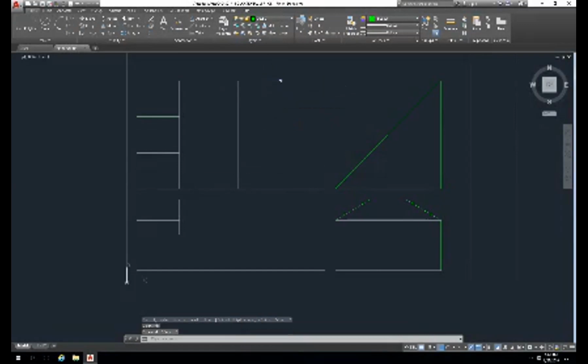So okay, we're out of the offset command. Well, 230 divided by 2 is going to be 1.15. So there are different ways of finding the middle line too. And then we've got 0.78 as the width, which is 0.39 offset. So we do offset .39. There we go. Strange. See, that's what I mean, sometimes it asks you before doing the offset, sometimes it's asking you after doing the offset. And then we have a distance of 1.12 offset.